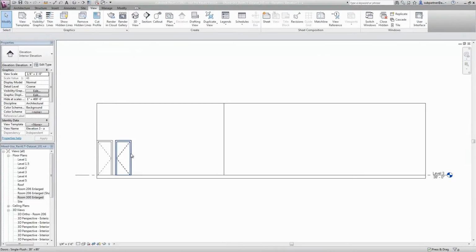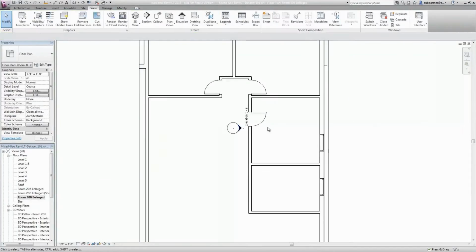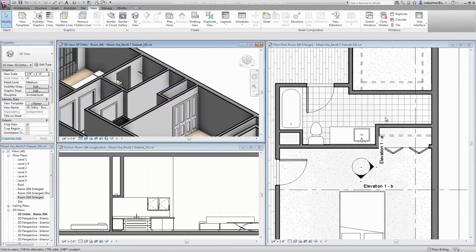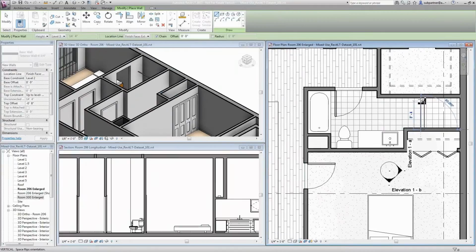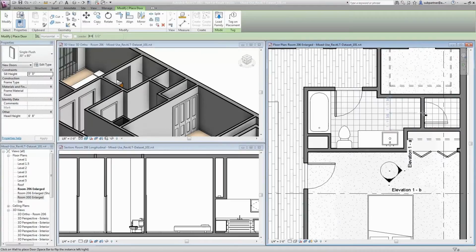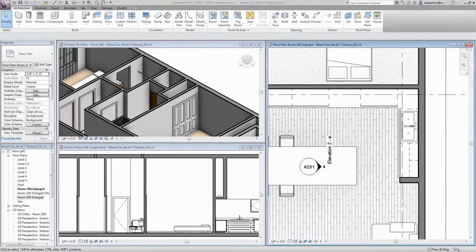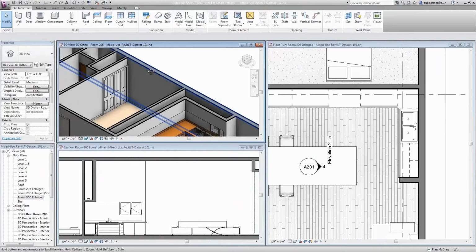And here I am in this extent of the view, and I can move this door in the section view. But again, these views are interconnected, so they know about each other. So as soon as I'm moving something in one view, it's immediately reflected in all other views, which is very important. So let's have a look. Now I want to draw another wall. I click the source wall as a property, and immediately I'm creating another wall with the very same properties, with the very same conditions as the original wall. And this way, it's very easy to continue to make a design.